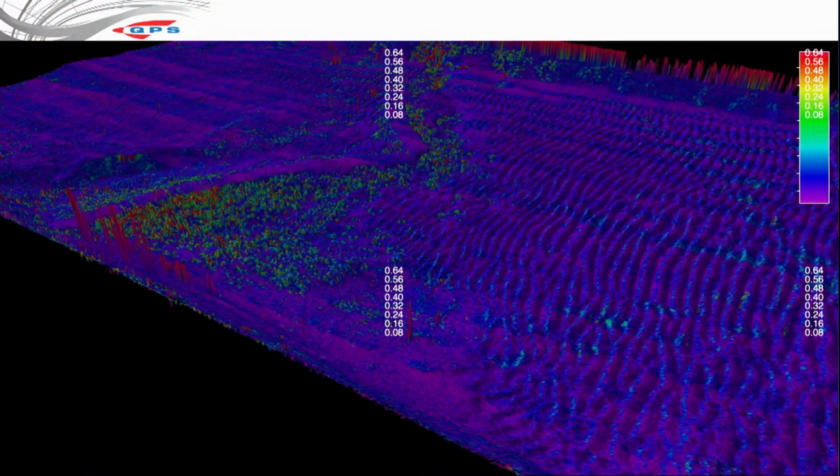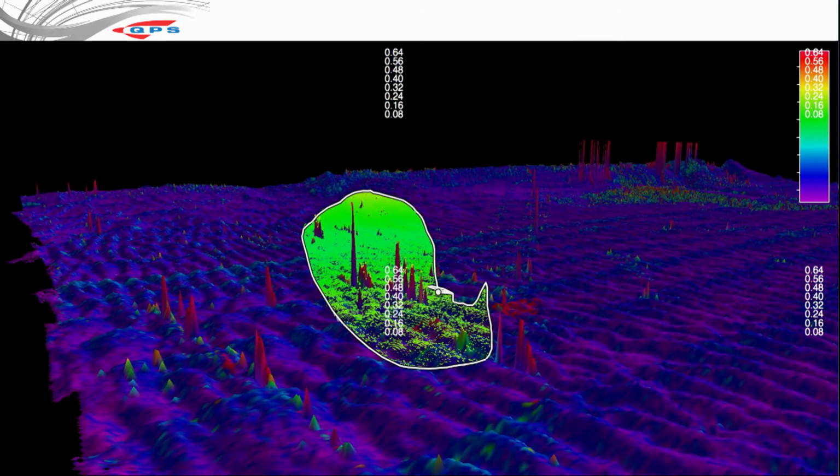And then it's like, okay, let me hone that in even better. So rather than looking at just color coding it by depth, let's go ahead and color code it by the standard deviation of the seabed itself. And then spikes start to show up even more, or anomalies in the data set. And now I zoom in, I go, okay, well now I got to get rid of these data sets. So now we could just start using really simple tools. We could draw a line around these data and then quickly get rid of them,